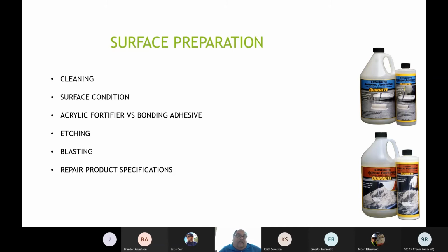Because when you're using a curing agent versus a sealer that you poured on the concrete, they have a tendency to go a lot deeper than if you put it on a pre-existing slab. So if you have a curing compound that you put on green concrete, the fresh concrete, you might actually have to grind a layer off. You might have to rent a floor grinder, and that's unfortunate because now your cream layer's gone off the top, and you're going to have to figure out some way to make sure right away you get some type of sealer or a resurfacer on there to protect that from further damage.